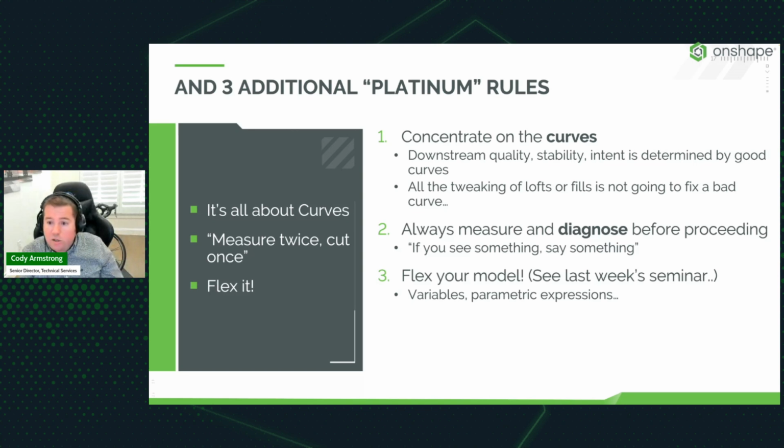And then if you haven't built the design intent in to handle those changes well, you've created work at that point, and extra work, because there's lots of references that need to be reapplied if you make dramatic changes early on. So flex your model. What I mean by that is make changes to it and see how it behaves, see how it fails. Does it fail in a certain way at a certain point when I reach a certain dimension? And am I ever going to reach that?